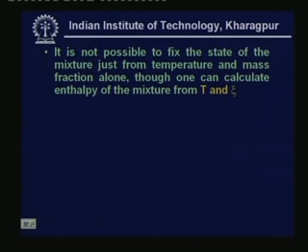Okay. That I will discuss a little later, and also it is not possible to fix the state of the mixer just from temperature and mass fraction alone, because one can calculate enthalpy of the mixer from temperature and concentration, but you cannot say whether it is in superheated region or subcooled region or saturated region or two phase region just by knowing temperature and